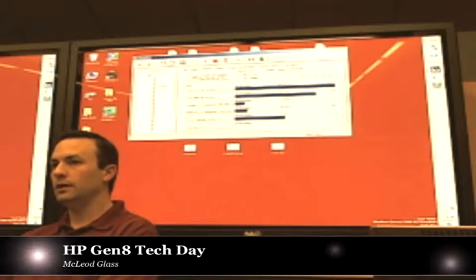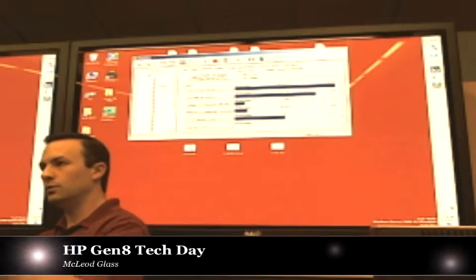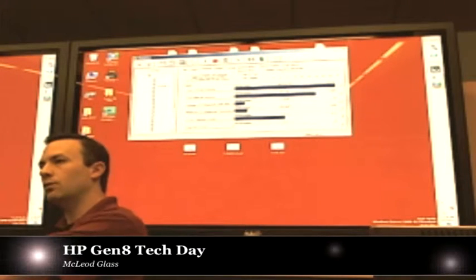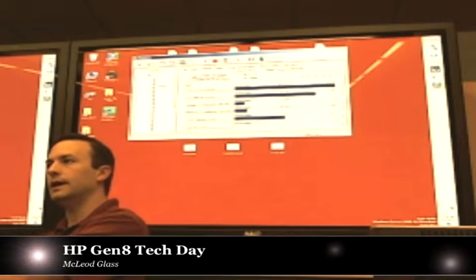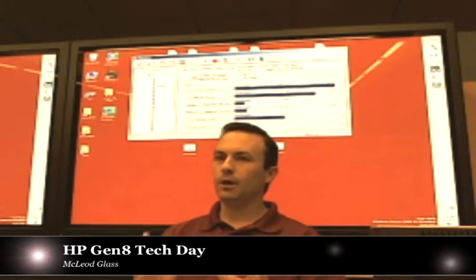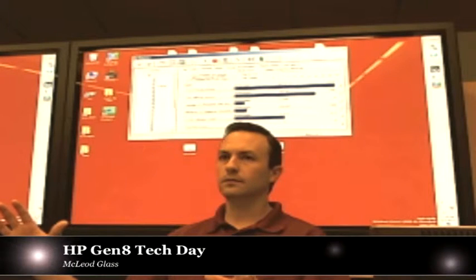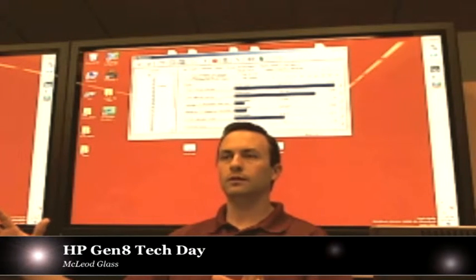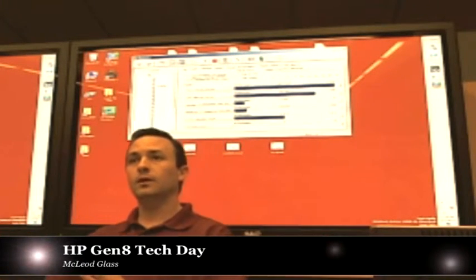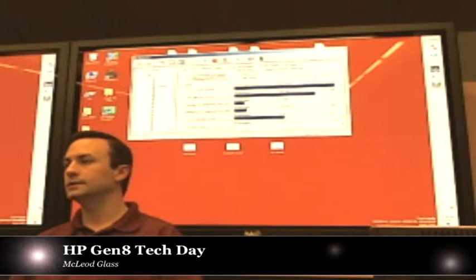We've got to intercept that data, calculate the XOR, and then by doing 2 reads, calculating the XOR, we write your regular data, plus we do a second write to update the parity data. So we keep our eyes on our XOR engine, our DRAM bandwidth, to make sure that we can keep up with the performance as we're performing those writes.